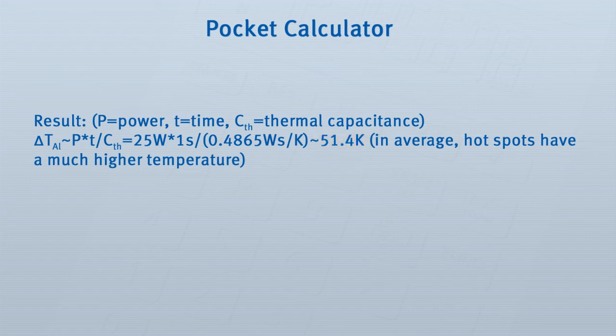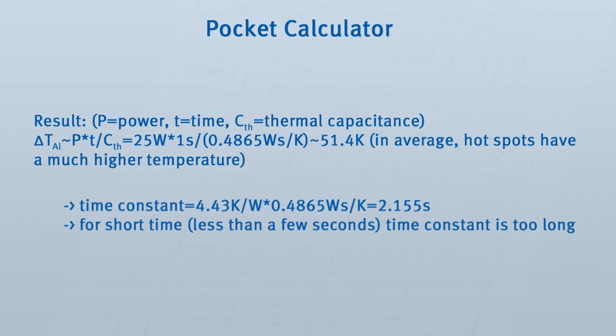But if we take the complete setup, we will get a time constant of more than 2 seconds, which is, compared to our 1 second pulse, too big. So that means the reality is somewhere between the first time constant, 44 milliseconds, and the second one, 2 seconds.